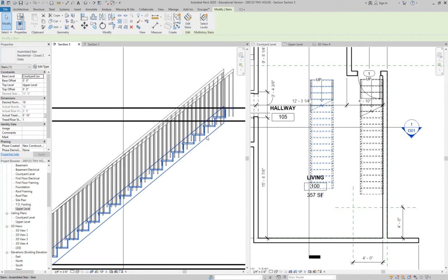So Carol, this is where you might find out that those risers that were supposed to be 11, maybe they were really 9 inches. Right. And they're just really steep stairs because when I look at it, I'm like, there's no way, 11 inch, right? Unless the floor to floor height is really low. That could be the other thing. Because when we did our section the other day, we accounted for about 12 to 18 inches of structure, and then anywhere from I think 18 to 24 inches of the plenum.